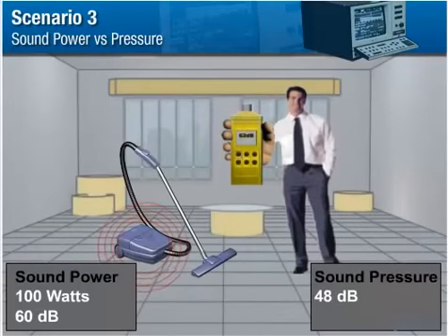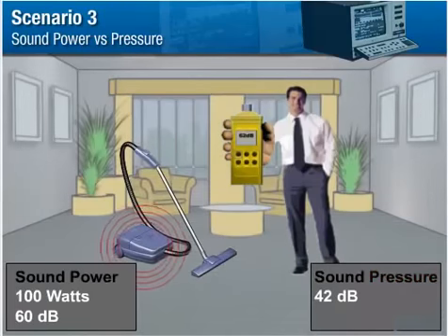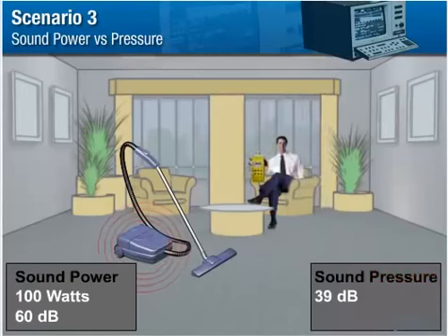The sound pressure levels recorded are greatly affected by the room. Cement, glass, and tile surfaces will tend to reflect the sound back into the environment. Items such as furnishings, wall hangings, and floor coverings will tend to absorb sound. Your location and distance from the sound source will also influence the sound pressure measurement that you make with a VU meter.